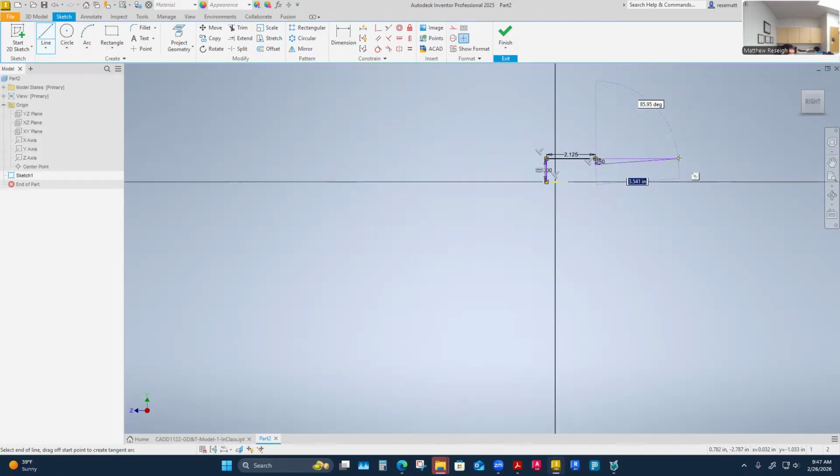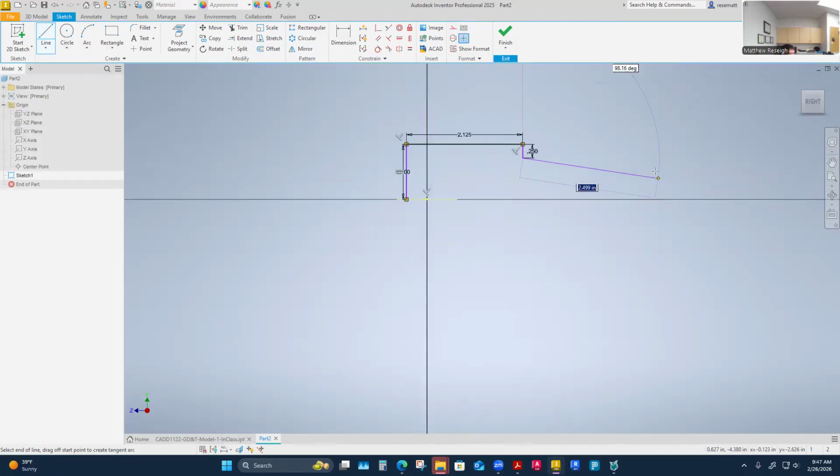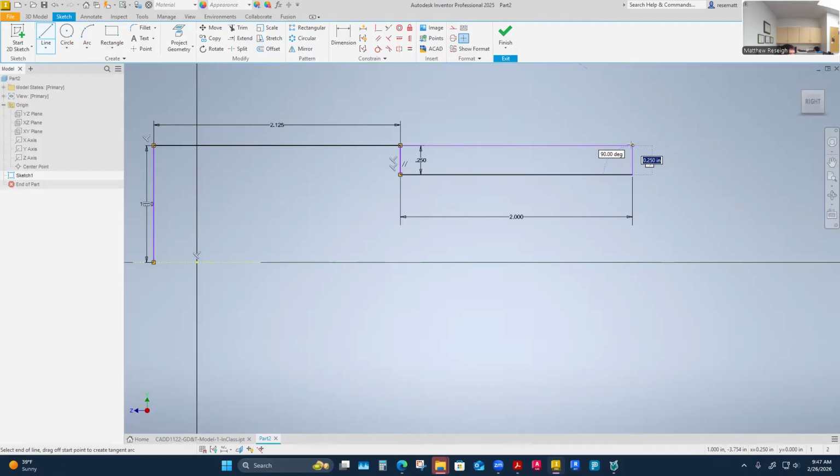And then what do we cross this way? 2 inch. And then back up again, the same. Yeah, these are on the same plane here. So the overall size from left to right of this part is the same, 2 inch in diameter. So there's 0.25 inches. And then this way I finish off at, I have a reference dimension on my drawing, 0.875,